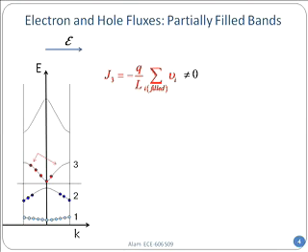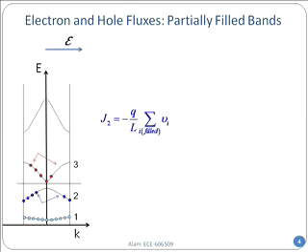Now let's focus on the blue one. What happens in the blue one is, again, of course, if you apply an electric field, but remember, these are electrons, which is fine, minus q charge, but these have negative effective mass, so they will move in the opposite direction. And as a result, when the electrons in the valence band move in the opposite direction, correspondingly, there will be an asymmetry between the plus state and the minus state, and together, once again, there will be a net current. But there is a very nice way to think about this, and that's something called a hole. And let me discuss that.